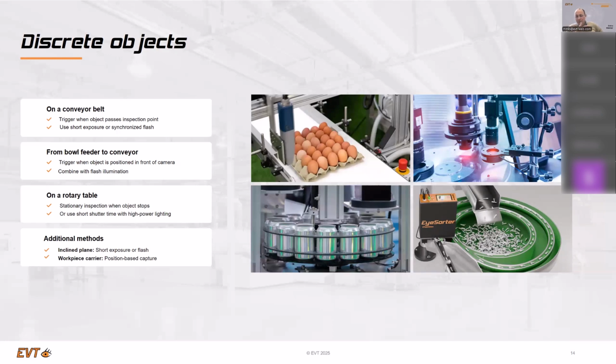And nowadays, of course, with an AI, even with a not so good illumination, the AI can count the eggs or can do the image segmentation or the image recognition, the egg recognition, let's say it this way. And you can make very easily an egg counter. So even with a not high-speed system, because the egg recognition could also run on very, let's say, low-powered CPUs. We saw it before. A Raspberry Pi with a color sensor would work perfectly to do this kind of task.